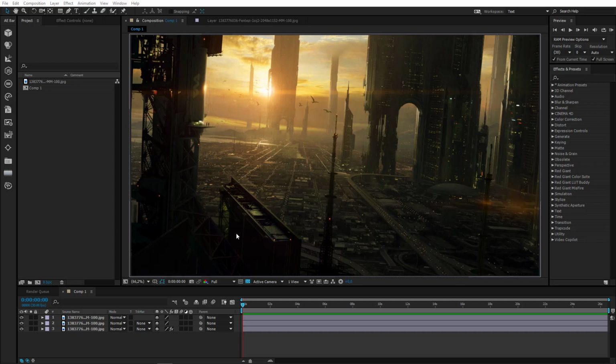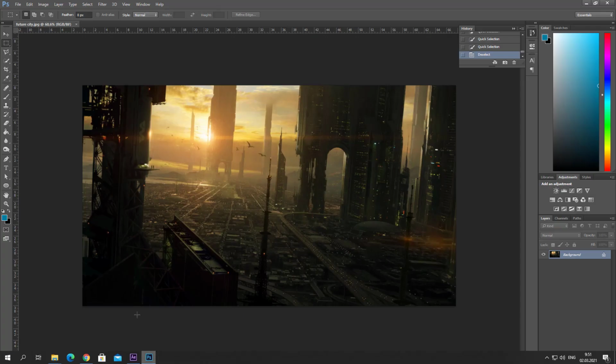So as you already know, we should model all of these buildings. We can do it the usual way, as we always do, which is to model all of these small details on the buildings there. Or we can create a rough mesh and use our clean edges feature. So this time we're going to try and do that, and that means that we'll be using clean edges. But in order to be able to use clean edges, we'll need to do some preparation in advance.